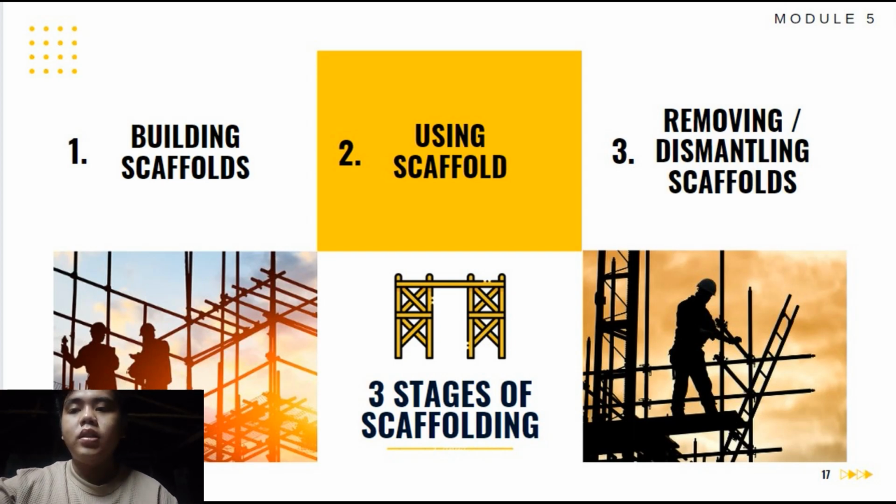Defective parts must be immediately repaired. Provide scaffold tags. For the last stage, removing and dismantling of scaffold must be done by trained personnel. Proceed in reverse order to its erection.